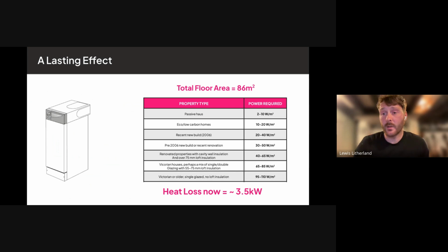And there's that table that we showed last week on the heat loss, the rough overview to calculate that. What I'm trying to emphasize here is when I installed the new boiler, which is a condensing boiler, did I change any of the rads? No. Did I change any of the pipework? No. What did I do? Did I even do a heat loss calculation? I'll be honest, I didn't do a heat loss calculation. I ran the tap and saw how good the flow rate was, and then fitted a 28 kilowatt combi.